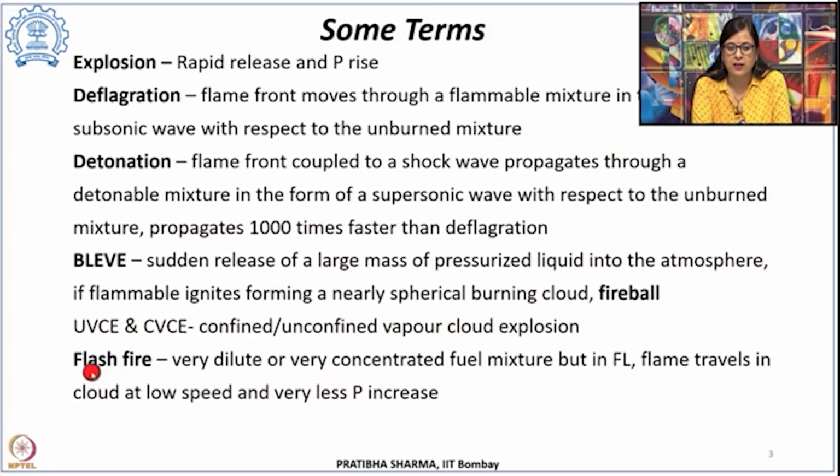It could be a flash fire. In a flash fire, if a very dilute or very concentrated fuel air mixture, but which is within the flammability limit, ignites, then it forms a flash fire, and that flame travels in the cloud at a low speed and at very low pressure.